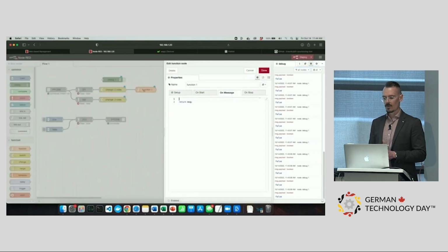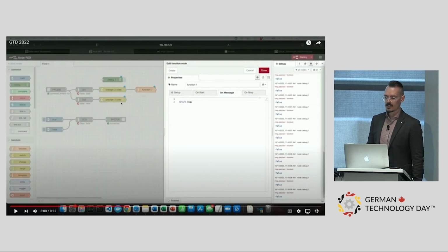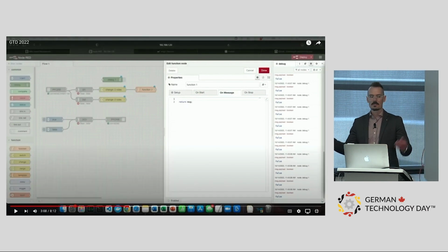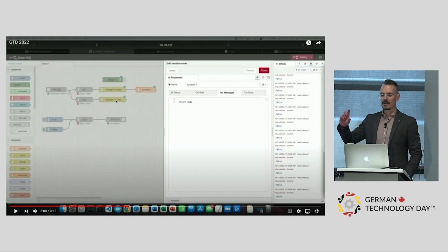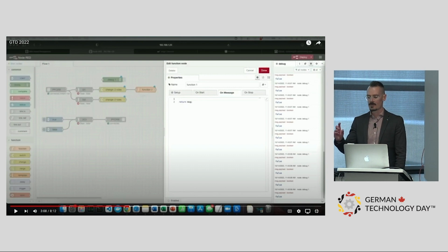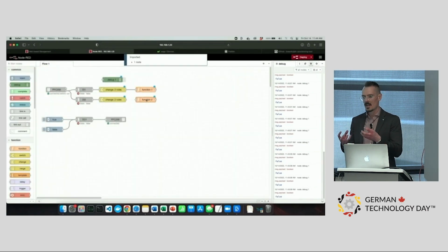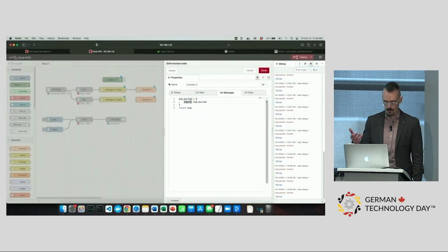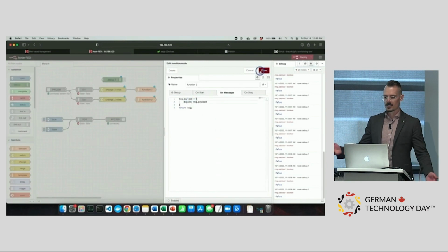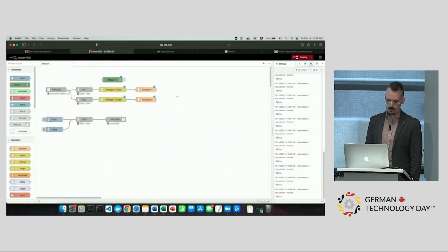This is, I think, the one part where it gets a little tricky. If I send number values to Ubidots, that's cool. It's getting a number value, but it doesn't know what's the variable. Like what is this information coming from? Which IO point is it coming from? I have no idea, right? So what I'm doing is I'm taking that number 1, and I'm going to set it into a structure, an object, so that it knows where that number 1 is coming from. So when I do send it via MQTT to the cloud, it's going to know what that variable is called, and it's going to give it a name. So I just created a name for this one called digital input 1. The other one I just called digital input 2. Cool.